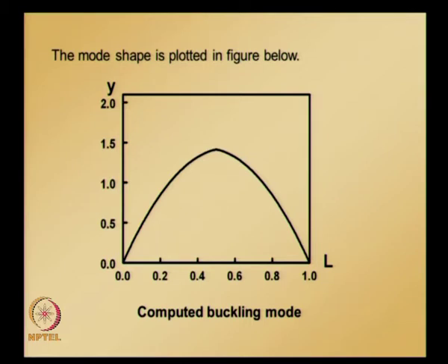So, now we have seen one application of this general one dimensional boundary value problem, which is column buckling problem, and you have noticed that the evaluation of these integrals when we are solving this problem becomes simpler, because J happens to be a constant. If J is not a constant, then the integrand becomes complicated and we need to evaluate these integrals using some numerical techniques.